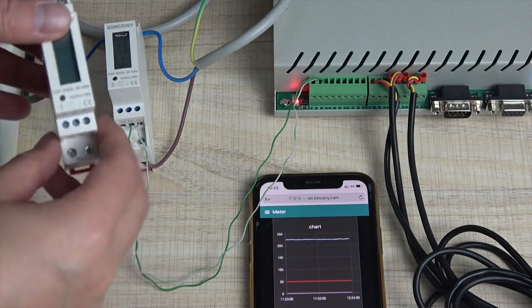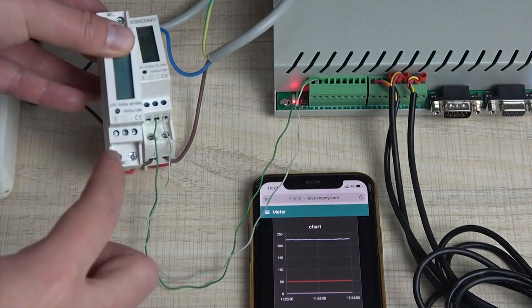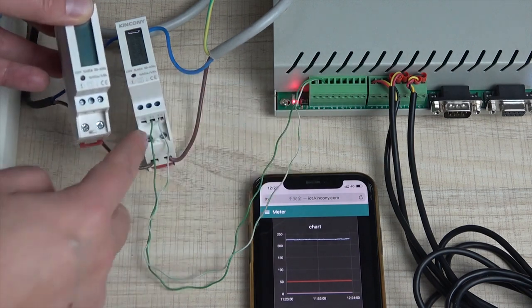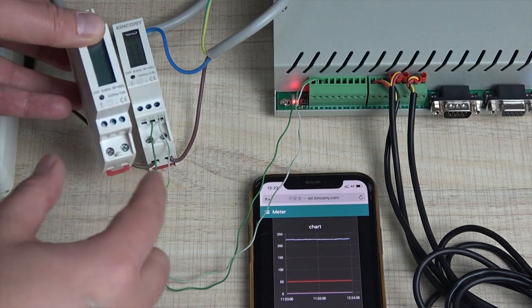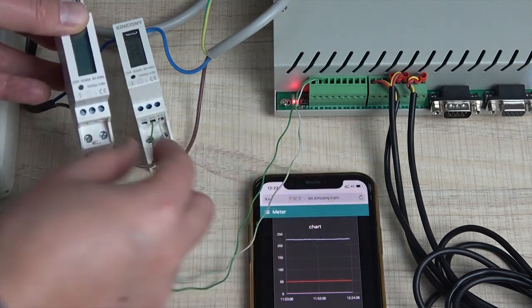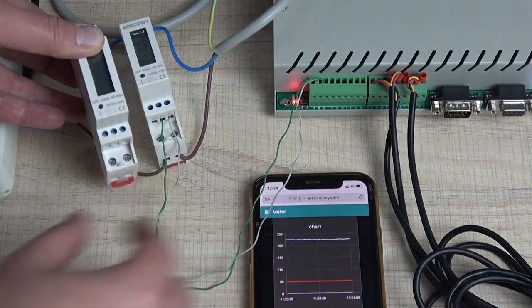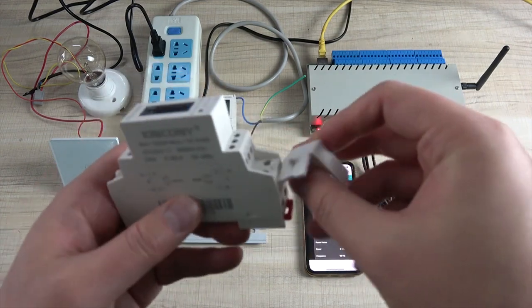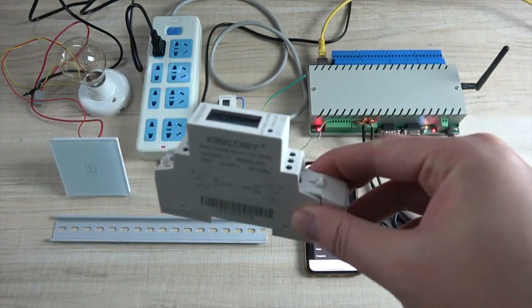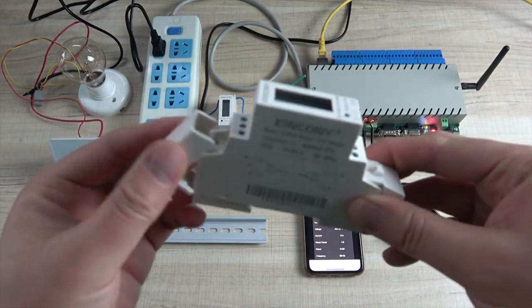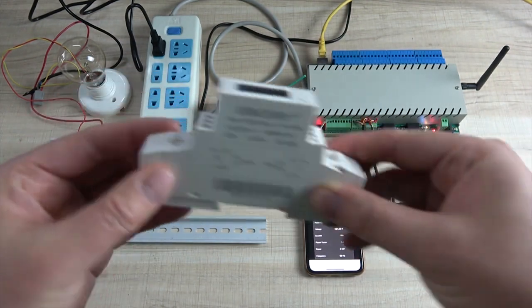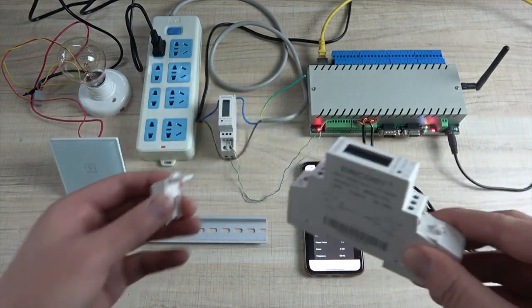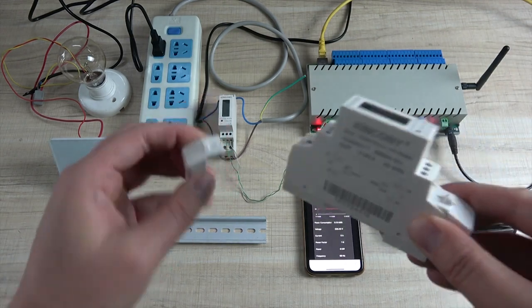If you want to use 2 meters, 3 meters, 4 meters or many meters, you just connect all the A with A and B with B together. Just use 2 lines to connect them together with A and B. It can communicate with multiple meters. When you complete the mounting, you can use this protect case, like this, to protect the line. Because I am taking this video, I have not installed this protection.